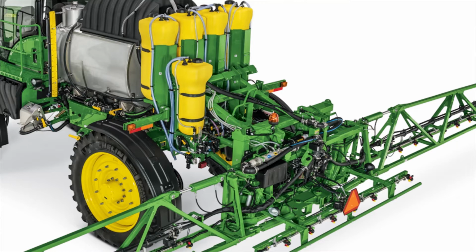Where customers really find the advantage of having a direct inject system, Dicamba's been in the news a lot. We talk about it a lot on this webinar as well. But by having a product that's a restricted use, for instance, we can keep it in a smaller 50-gallon tank, not contaminate our solution tank, and turn it on and off at will without having to do as extensive of a rinsing process.